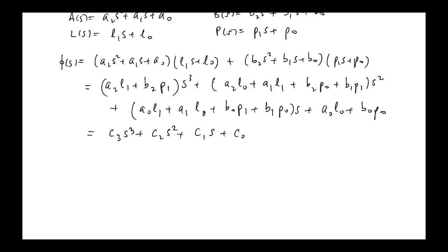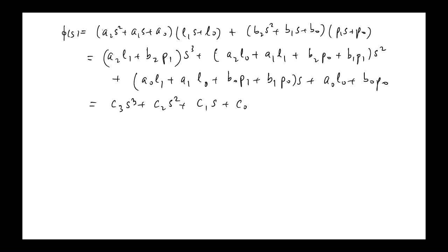So if you just write that out as a matrix equation where each row corresponds to matching one coefficient in the desired characteristic polynomial, right? So we're going to just write down a little vector of those coefficients, C2, C1, C0. Okay, so that's the result that we want.